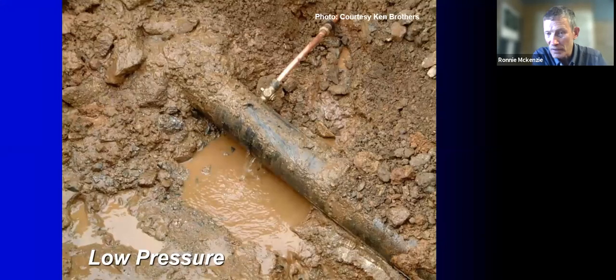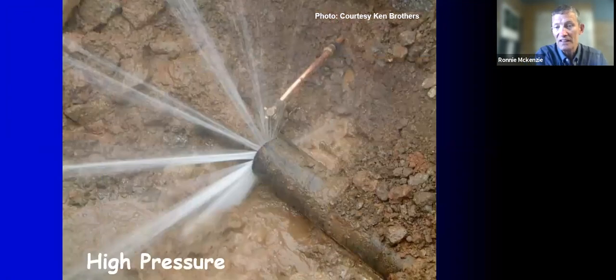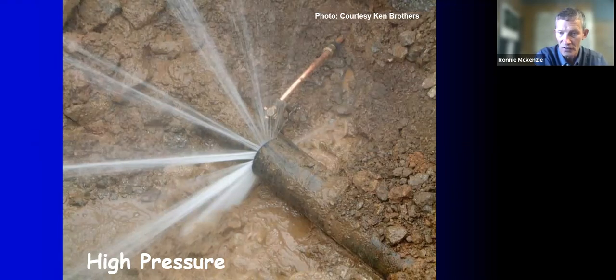We always use this picture. This is from a good friend of mine, Ken Brothers. I think everyone uses this one now. This is just a leak from a main at a low pressure, and this is the same leak at high pressure. So basically, what we're saying is pressure drives leakage. If you can get the pressure under control, you will do a lot to get the leakage under control.